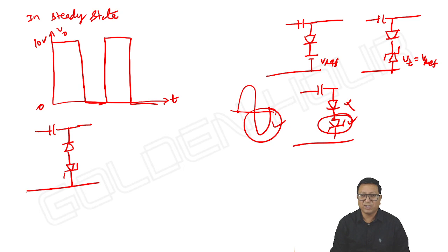Suppose I want to have a negative reference voltage with a negative clamper, and that too, that negative reference voltage in terms of the Zener diode, it is not possible. And again, in positive clamper, negative reference is possible. Once the Zener diode undergoes breakdown, definitely it will maintain a voltage Vz which is equal to V reference.